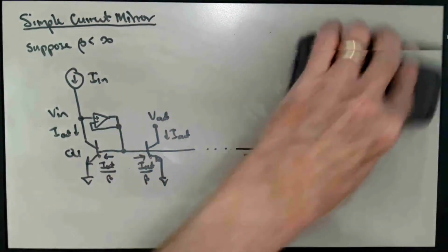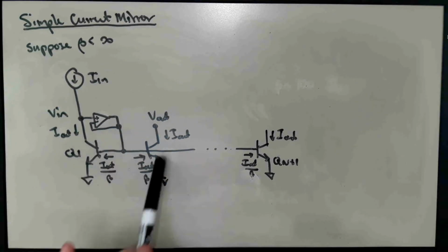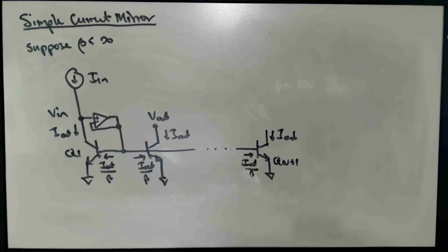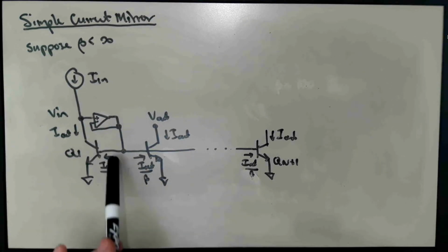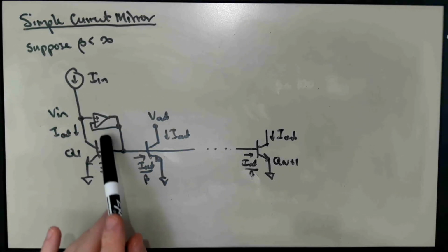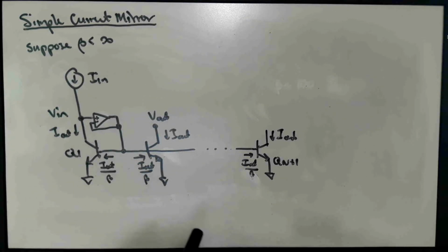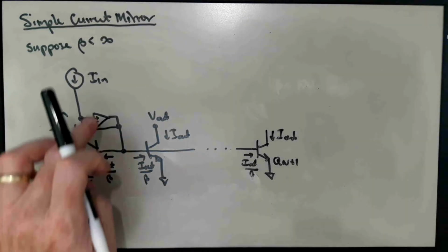Now, this may seem fine, but often a current mirror is actually an internal component in making an op-amp. And so you might be wondering, do we have something of an infinite regress here, because we need an op-amp to make a current mirror, which is part of an op-amp? And the answer is no. Sometimes we will make sort of crude op-amps and embed them within fancier op-amps to improve their performance. That's actually done quite often.